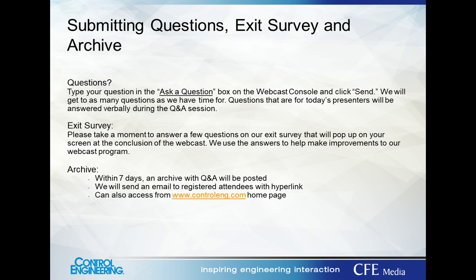Here's something to remember for those people who are maybe more at the introductory level of APC. Model-based control is essentially feed-forward control, and model-less control is essentially feedback control. In the course of developing our MLC tools, we've patented some algorithms that are especially suitable to the multivariable application. But basically, model-less means feedback. That's the easy way to remember it.